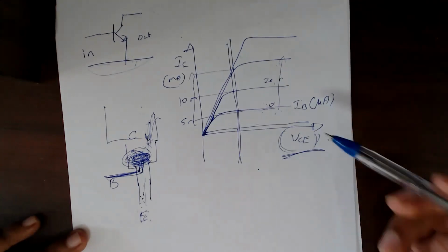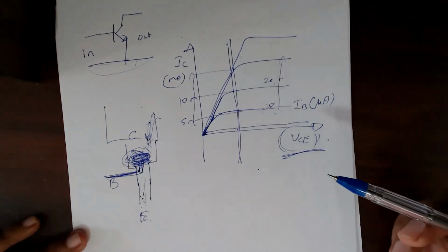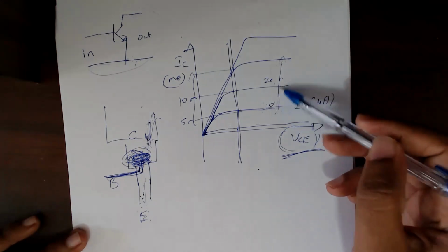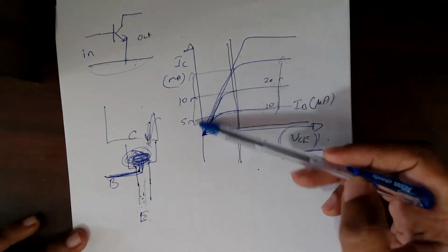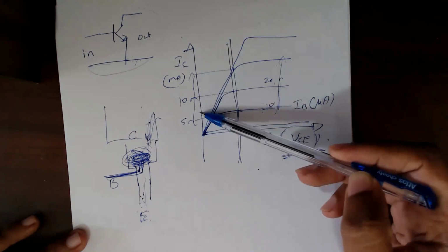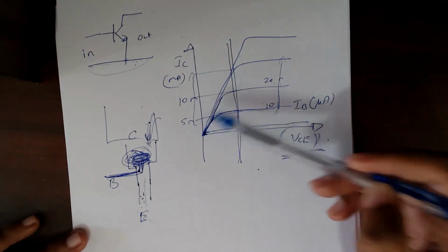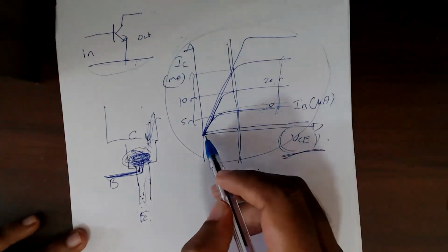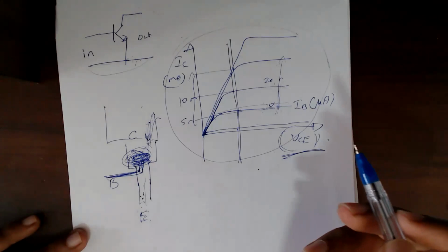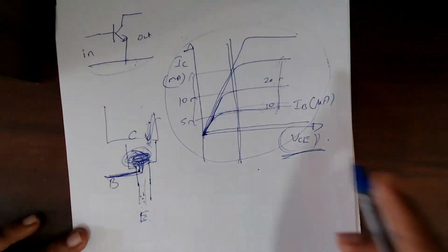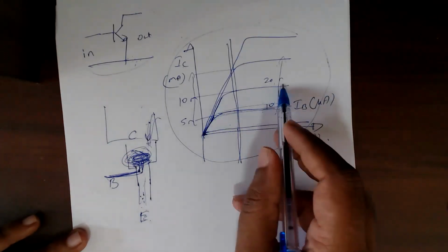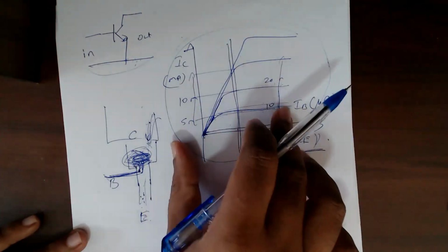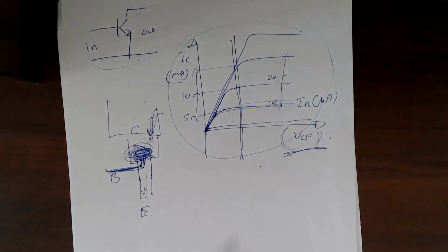So this is why it is called an active element. This is why it's able to amplify the signals. You are supplying only 10 microamperes, but it's able to control around a 5 milliampere signal. Right? So this is the output characteristic. So you are basically measuring the output characteristic for different input values and plotting it in the same graph. So this is what the output characteristic is.